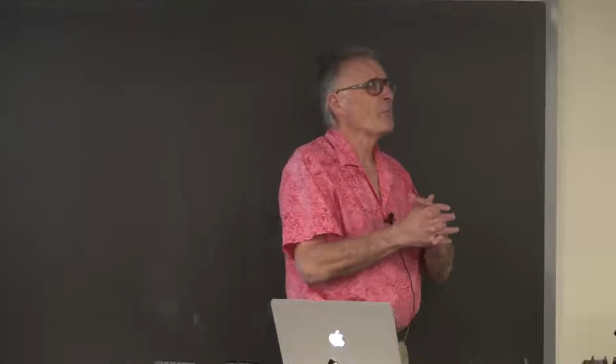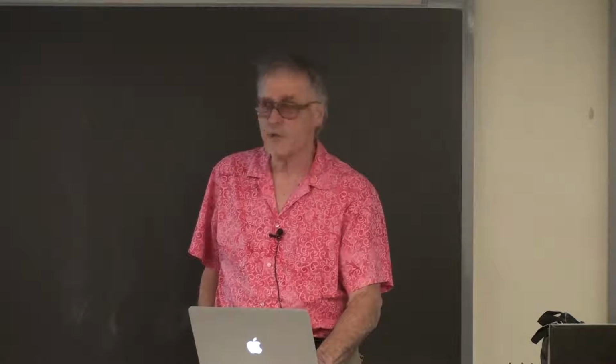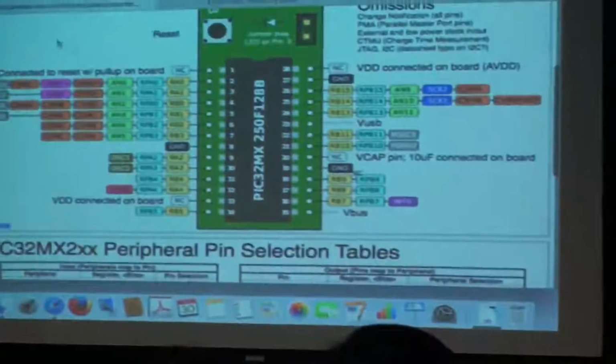PB4 and PB5, port B4 and B5, have some special functions that were messing people up when they tried to use them for chip selects. And so I thought I'd talk about resources that are available for figuring out what in the heck pins do. And the resource a lot of people have been using is this, but this is a simplified version for quick reference.